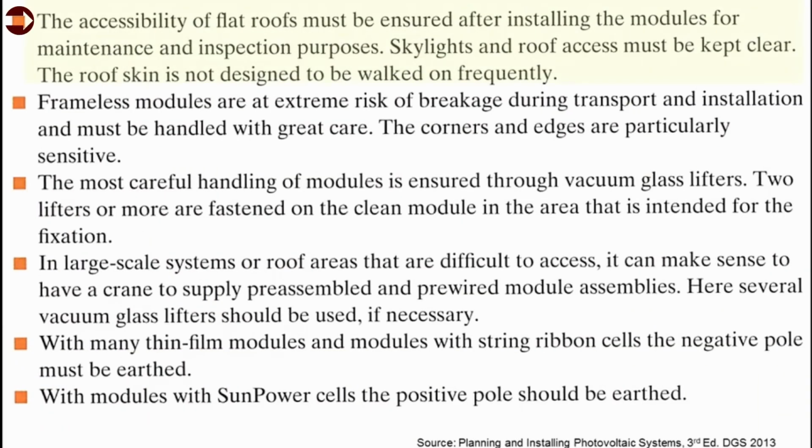The accessibility of flat roofs must be ensured after installing the modules for maintenance and inspection purposes. Skylights and roof access must be kept clear. Frameless modules are at extreme risk of breakage during transport and installation and must be handled with great care. The corners and edges are particularly sensitive.